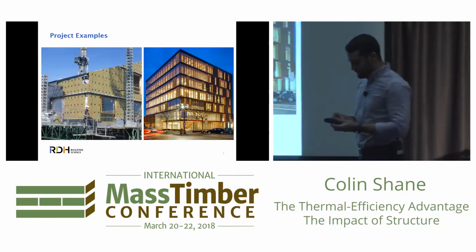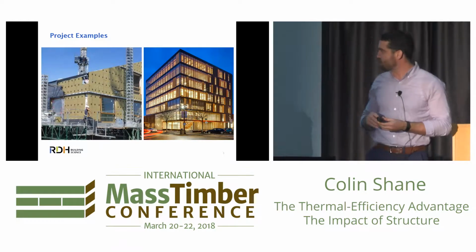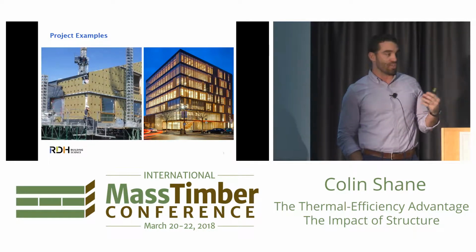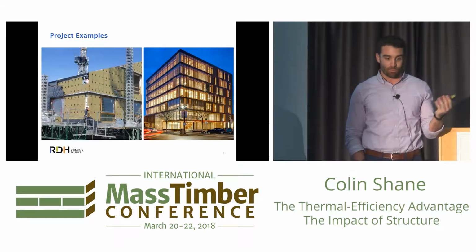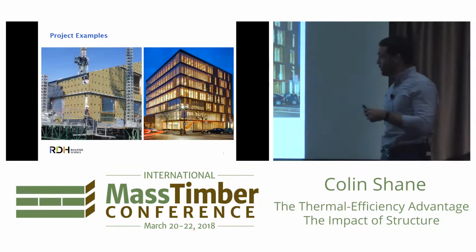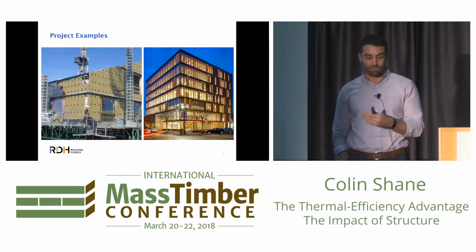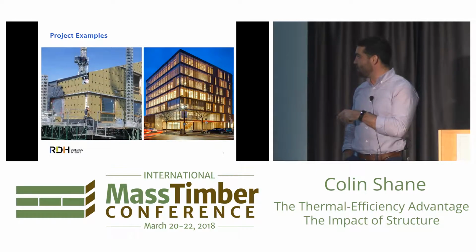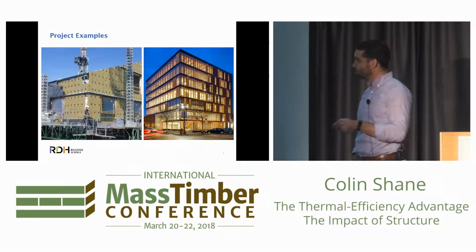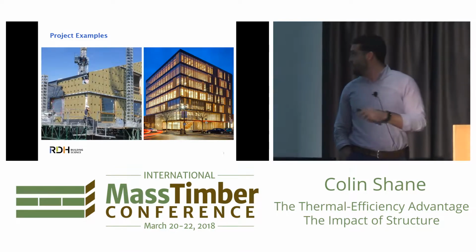I have had some good fortune of working on some really interesting CLT projects over the years, mass timber projects. From a facade perspective, some of them are pretty basic. Some of them aren't that different than what we would do for a typical stick-built building or a concrete or steel building. This is a building in Vancouver. Doesn't look anything different from a facade perspective to what we might otherwise do. We have an air and water barrier in the exterior. We have a bunch of exterior insulation for thermal insulation, and we have a drained brick veneer on the exterior.